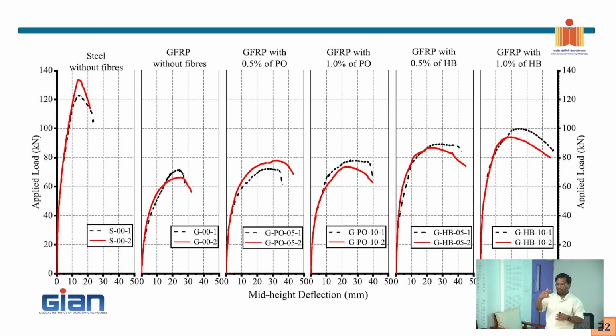So the fibers are helpful in improving the performance in multiple ways. One is the stiffness of the fiber, which helps me control the crack. In addition to that, it will undergo a slipping process, pull-out behavior, which helps me in dissipating the energy being put into the system. So in multiple ways, it is helping. But having said that, these fibers are only 30 mm, 40 mm, right? And they are anchored only over a small region.